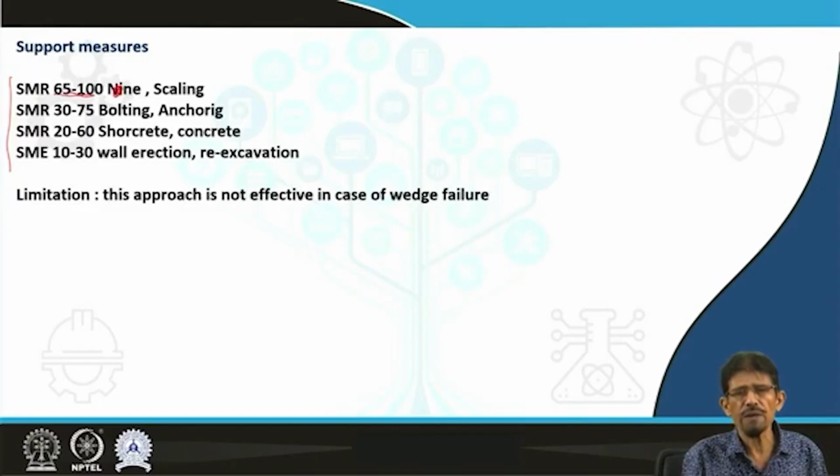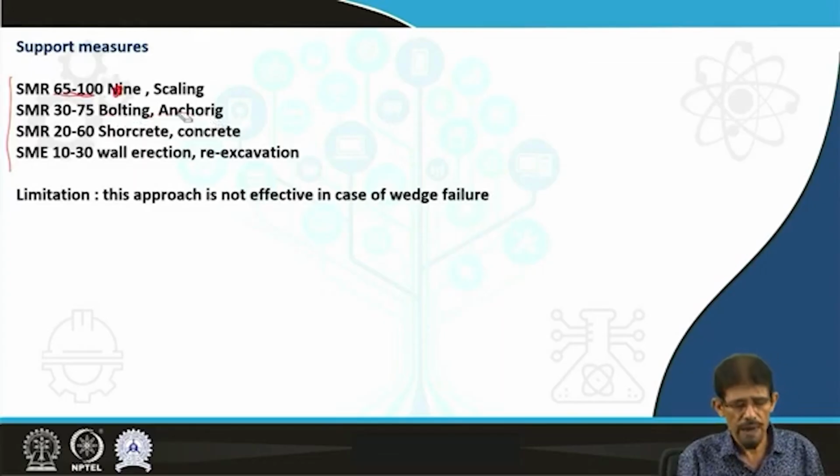Scaling required means we are going to take one rod and clean the face of the excavated zone or slope if required. SMR value 30 to 75 recommends bolting and anchoring to stabilize any slope made up of rock mass having value 30 to 75.